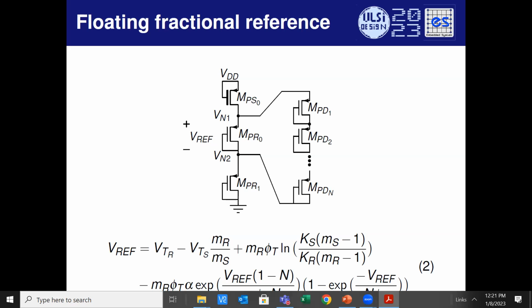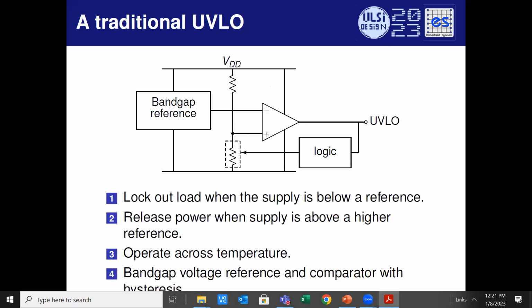What we further did was we divided up this floating voltage reference. We took a fraction, and now I can logically choose which fraction I'm going to take, compare against. Remember, we need to have 2 comparison points for this comparator, one higher voltage, one lower voltage.